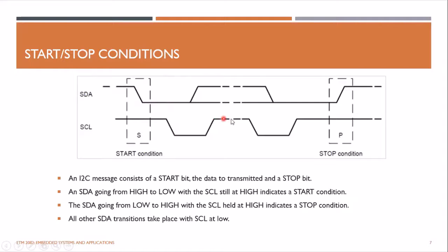Depending on the positive half cycle of the clock pulse, the data could be high or low, and it will read within this period. If it is high, it will read it as 1. If it is low, it will read it as 0. And the stop condition is, while keeping the clock line high, the master releases the data line, right?